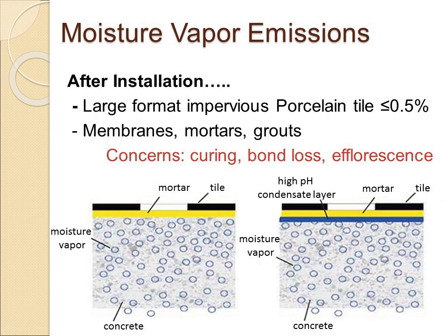So considering moisture vapor emissions is important. It's not something that tile contractors traditionally are concerned about because, again, we go back to floor covering, which has been more susceptible to these issues. But when we think about what occurs in a concrete slab, where you have a higher pH at the surface, you have alkalinity there where it's going to possibly cause efflorescence, cause expansive materials or minerals to form, then you could have failure or you could have damage to your membranes or damage to your grout. So all this is really important to consider.